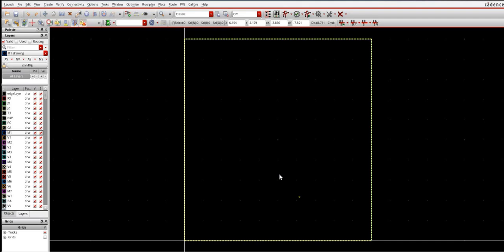Generally, whenever we are dealing with density related issues when it comes to FinFET related designs, it is very important that you check the base level density of your whole module, whatever you're working on, beforehand. Even before you clean up the base density, base DRCs, or even before you start the routing, just do the floor plan of your design, and then you can check for the base density. How to do that?